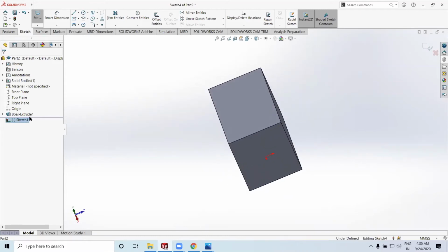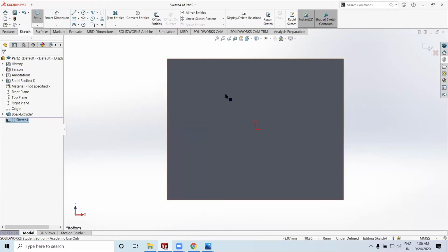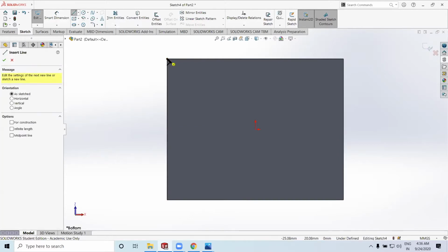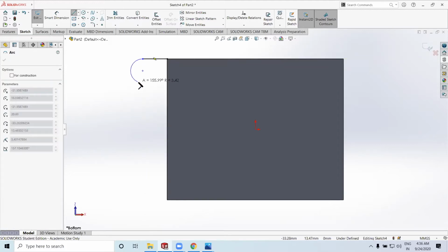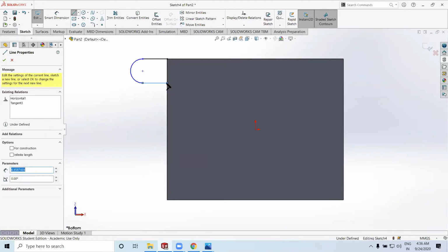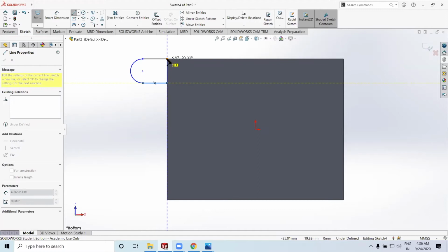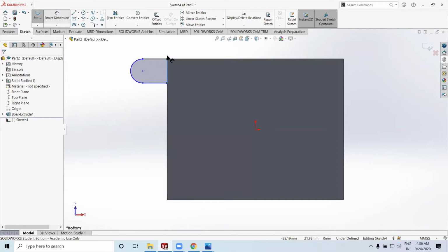Perfect, yeah. So we again use the line command, extend it, then hover around it, you'll obtain an arch shape figure again. Yeah, you draw a line over here, close the surface, now press OK. Now give it a dimension.